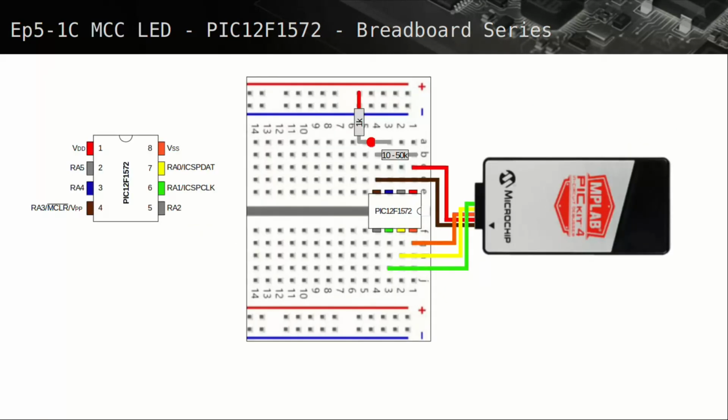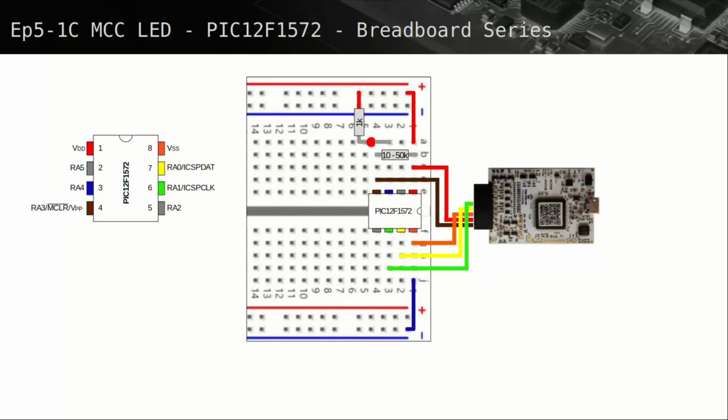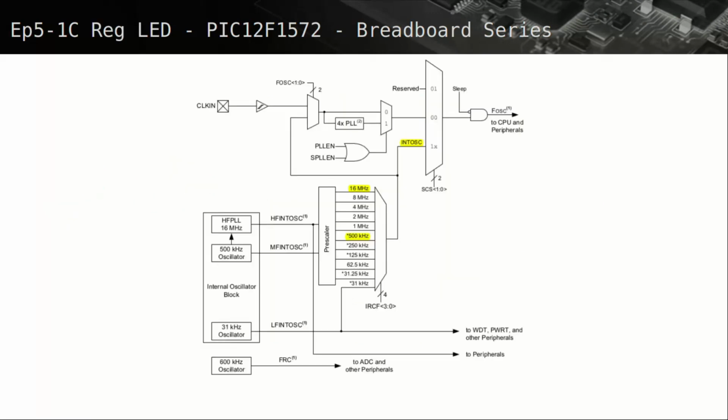The PICkit 4 and Snap can be used in any of the methods covered in the assembly part of the tutorial, with the PICkit 4 powering the device and circuit, or being externally supplied, or with the Snap programmer using an external supply. Then for another added part, the LED will also be toggled on and off, so we will need to use a delay function to achieve this.